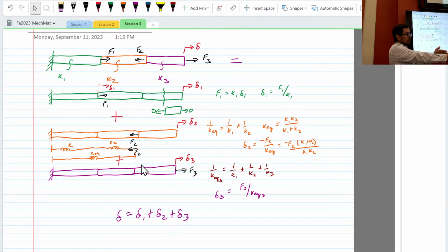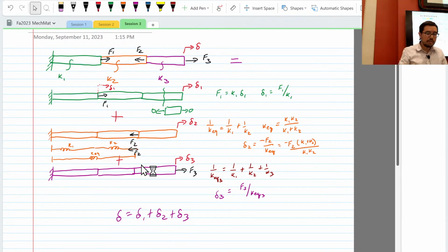Okay, and so the change in length, that's deformation. But if I look at the displacement of my wrist, that also has some stretch from my forearm and my bicep. So that's the difference. So now the question is, how do I figure out the deformation in the second region? That's what you all are asking. So how do you do that? Well, this is maybe a subtle point.